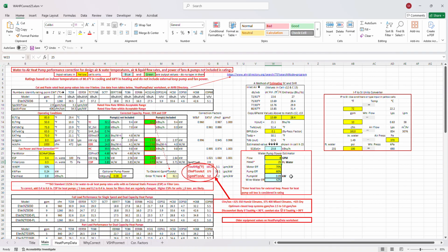So you can see it upped the kW to 0.09. So we'll put that in here as 0.09, and we'll see what we get. So we're looking pretty good. We got a machine that's a little less than 3 tons now, and we're good on the temperature, 101, and we're good on the SHR.